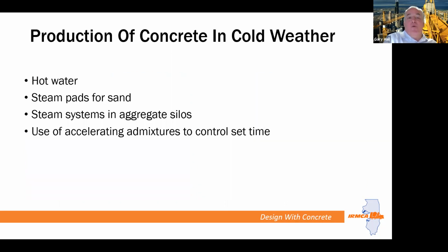Production of concrete in cold weather incorporates the use of hot water. We can even use steam pads for sand, possibly even steam in the aggregate silos like we may have in some locations. And then the use of accelerating admixtures to control set time as well. Next slide.